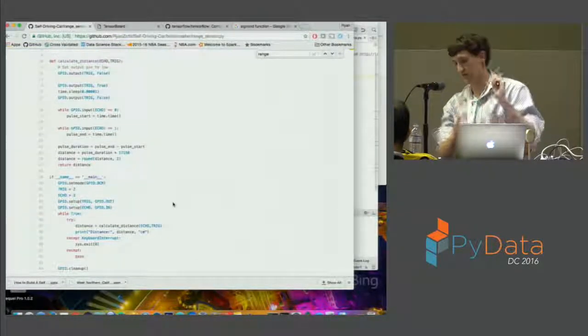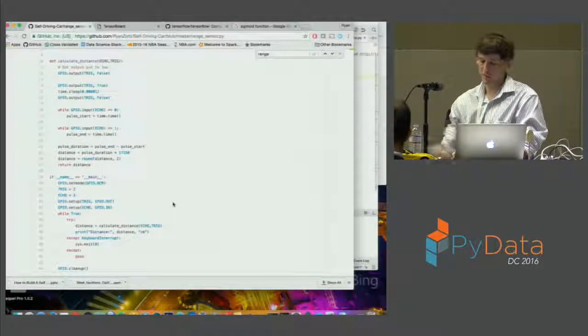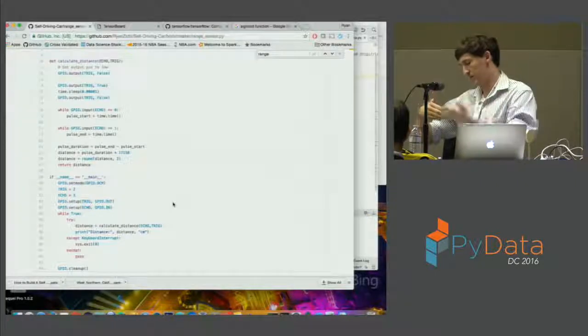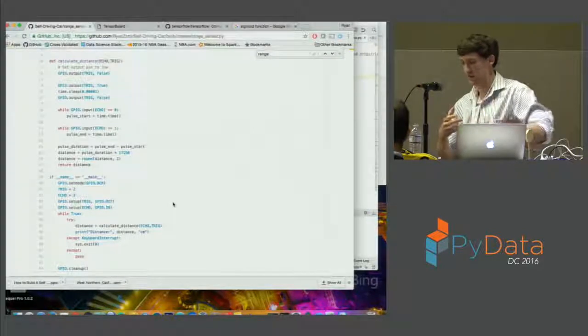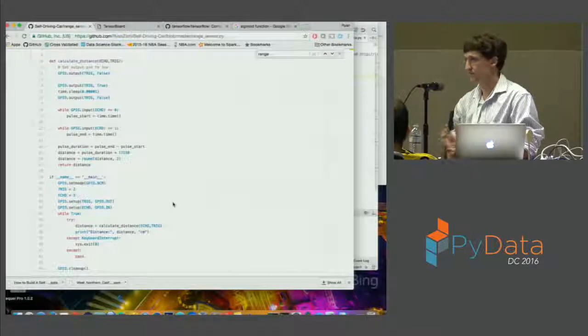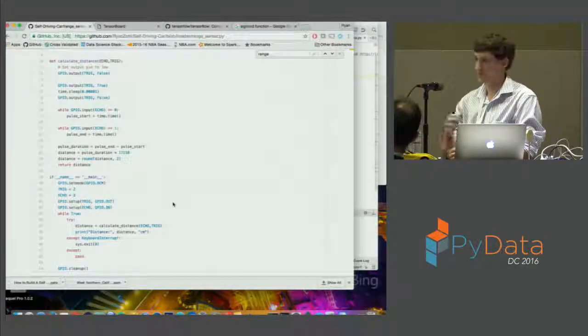I'm basically sending out pings really frequently, and whenever I get a callback, whenever I get the sound bouncing back, I calculate the time that it took to travel, and that's how far away something is. I'm running this process continuously in a loop, and if something is I think 25 centimeters away, I stop because I assume it's some sort of big obstacle. That'll override any command I get from the self-driving car neural network, pretty much.